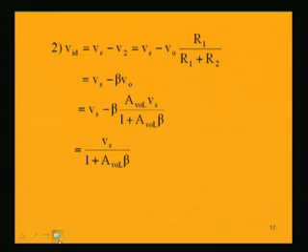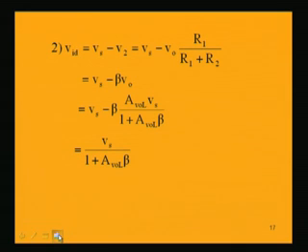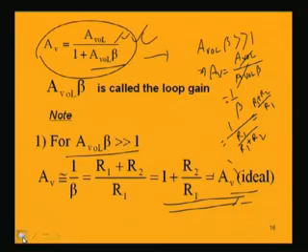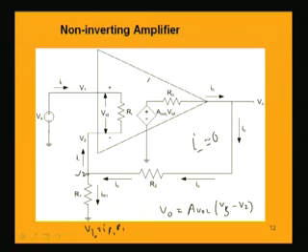So, if we consider exactly the practical case of a non-inverting OpAmp, we have the gain given by this term. So, the closed loop gain or the closed loop effect is coming here, and another factor to be noticed here is the difference voltage. Now, what is VID? VID, if we consider in the circuit, is equal to Vs minus V2.